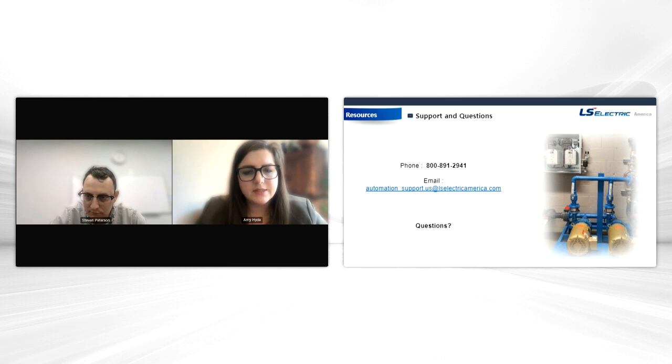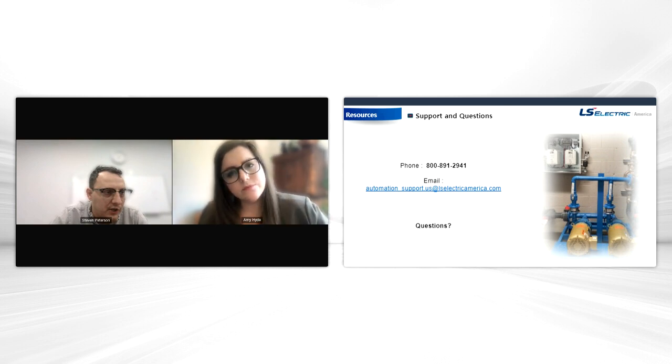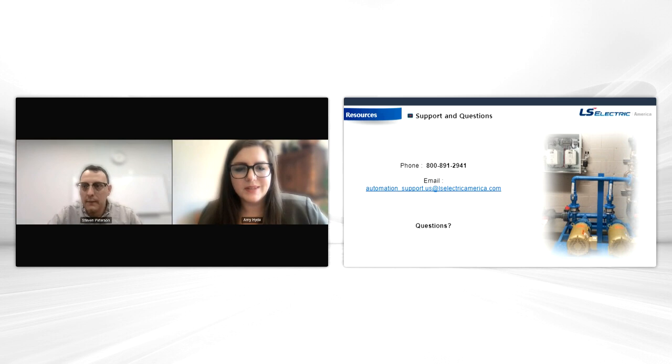One of the questions says, will lead lag pumps alternate, or will there be a fixed lead pump? Okay, yeah, so it can pretty much be however you want. By default it's a 24-hour alternation, which is what most people are happy with. If the lead drive is running for 24 hours, after that time it's going to automatically switch over to the other one. You could shorten that time, extend that time, or disable it so you don't need to alternate at all. So again, it's one parameter and you could customize it for whatever your needs are.